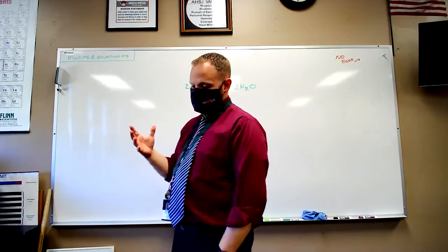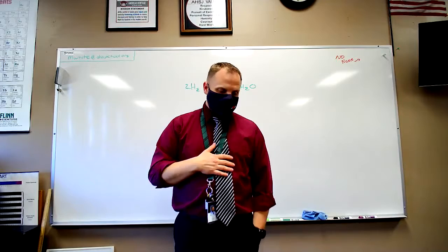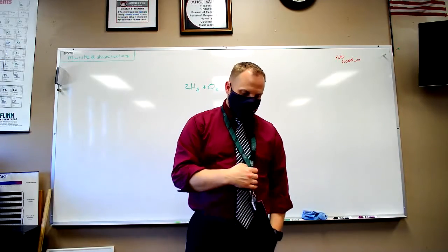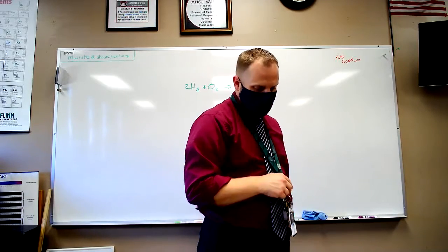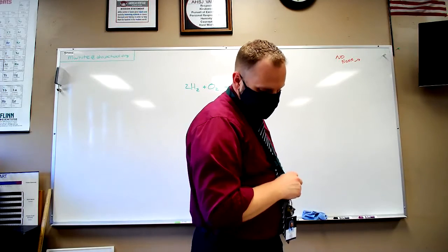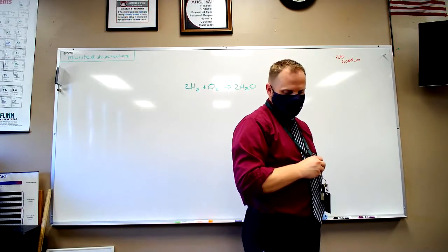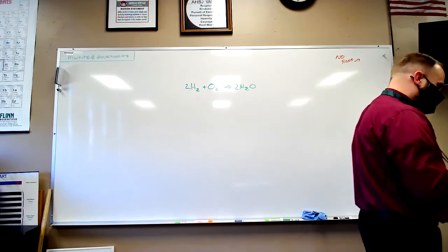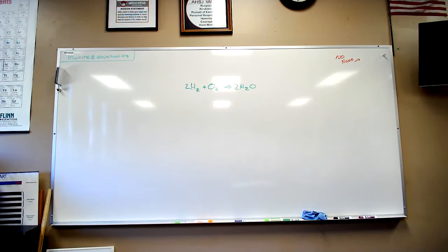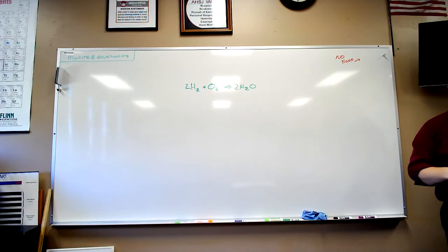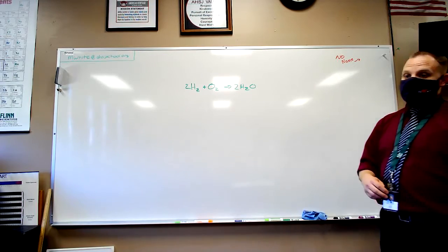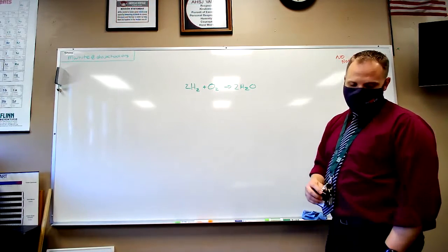Obviously, if you have something in water, that's going to speed the corrosion process. It will also speed the process if you have water which is rich in electrolytes, like salt water.